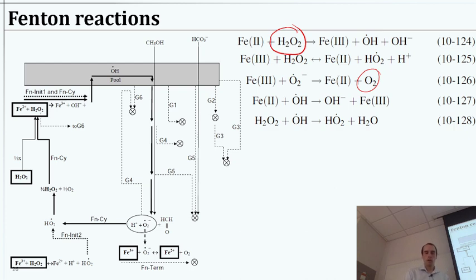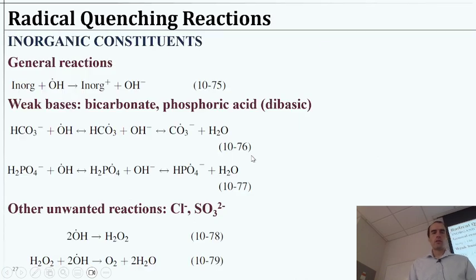It's a pretty well documented study. It's used occasionally. You could consider the fact that if we're going to use, let's say, ferric chloride or something like that for coagulation, you could also dump some peroxide in there in order to generate hydroxyl radicals and do some oxidation while you're doing coagulation, right? So it's interesting. I think it does find some uses. You'll definitely see it in the literature, in different scenarios. Maybe even in natural systems. Sometimes it becomes relevant. There's some naturally forming peroxide in natural waters. Not huge concentrations, but it's out there. So that's all things you could consider.